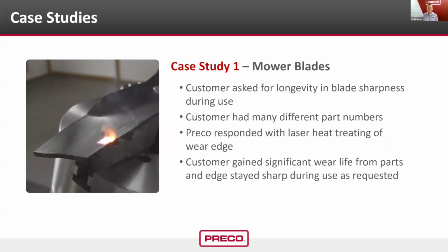And the surface hardness in the mid-50s Rockwell C. That's basically to reduce the frequency of maintenance on the blades, i.e. sharpening. The blade will see a lot of abrasive conditions, especially in the southern US where they're on golf courses, for example, with a lot of sand. And we effectively developed a laser process that could get that 1/2 inch band to